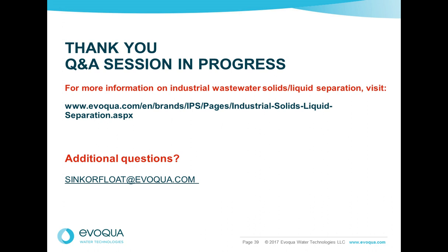So we need some ability to handle variations in hydraulic load and how it results in carryover. So we look at methods of that, and of course we mentioned one technology, but there are other ones that address upgrading the clarifier, like Biomag, to handle higher solids loading, at least in a biological system.